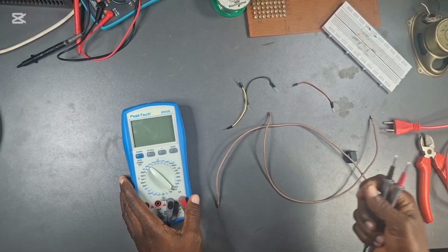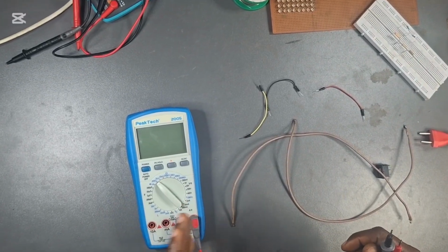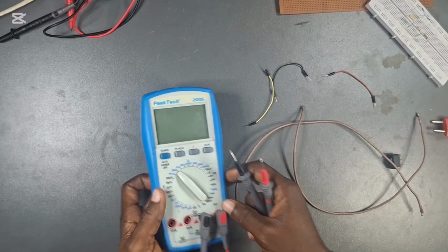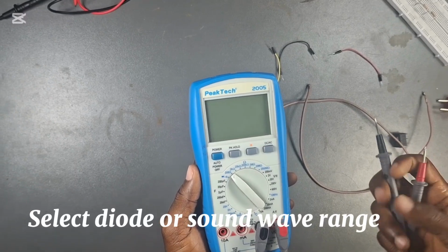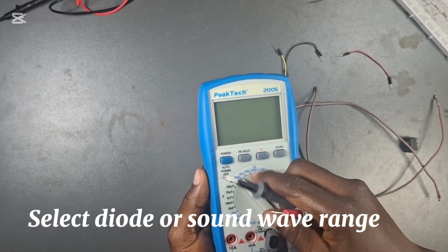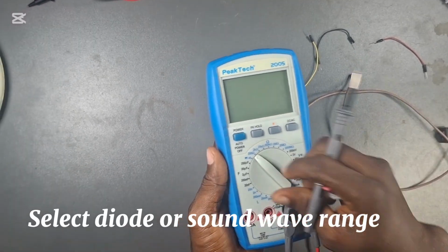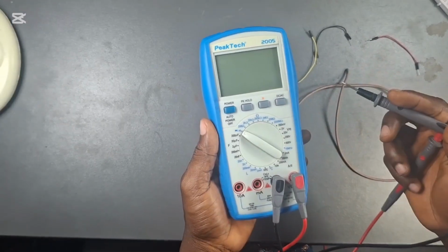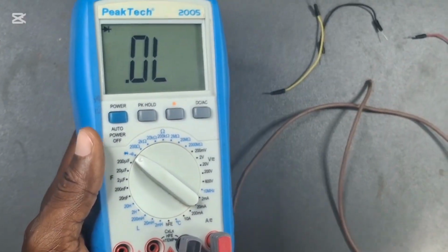Now, for continuity, we also have to select a particular range. We have a diode range on the multimeter, which we will be selecting for our continuity test, or the sound wave symbol. So we select that, and then we turn on the meter.